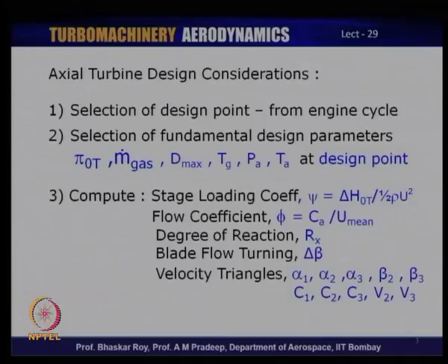And then of course, the turbine entry temperature T gas, or what in cycle analysis one would call T 03, or even in turbine discussion we have often called it T 03 or T 01, whichever way you look at it. So, that is T gas. Now, that gas temperature comes from the combustion chamber, and you need to have an idea what gas temperature you are letting out into the turbines.